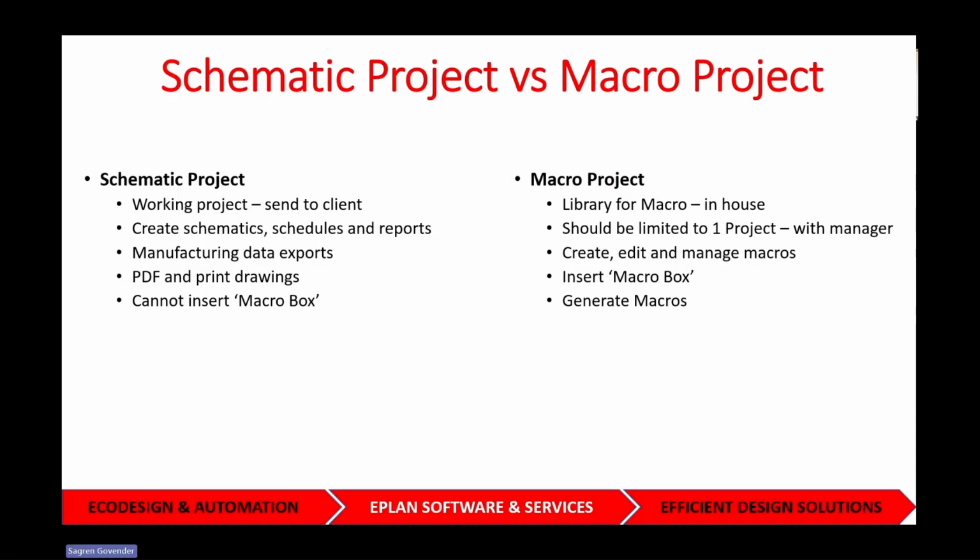And as I mentioned, the macros need to be generated. So once you create them, there's a button on macro and on Eplan, and I can show you where that is. And you literally press that, and you generate the macro. And it looks at the path where you want to generate that. You define that, and then you press a button and generate that macro, and it will reside in that location.